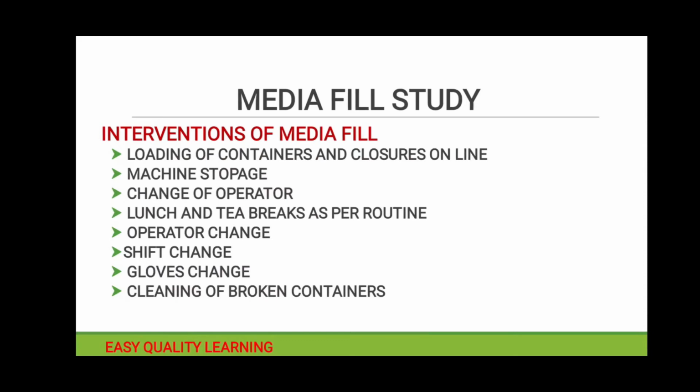We need to identify how many times we need to load containers and closures, and accordingly it should be done. Machine stoppage. In between, our machine stops for lunch time or tea breaks or something like that, and that needs to be simulated as per our routine practices. Then change of operators. If we have an SOP that our operator will change after 4 hours or after 6 hours, or during lunch time a second operator takes over, or during shift change a second operator takes over, then that activity should be simulated in media fill.